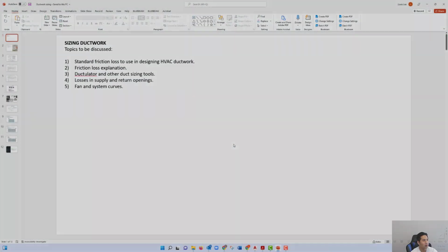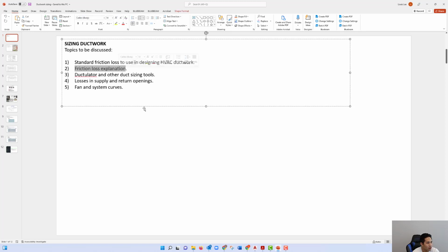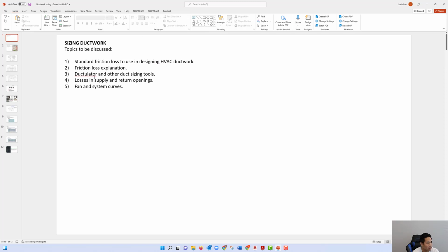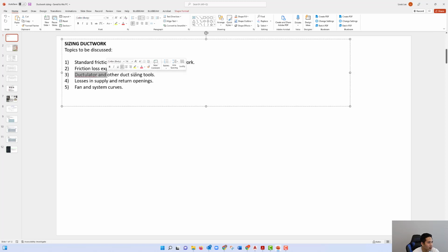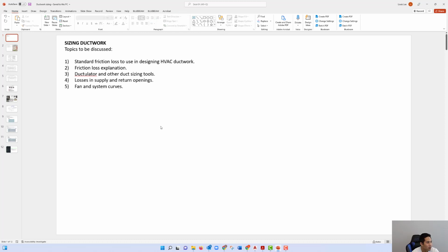In today's video, we're going to talk about sizing ductwork, and we're going to talk about these topics here. First is the standard friction loss that is used when designing HVAC ductwork. Then we'll go into explaining what the friction loss really is. Then we're going to talk about some of the tools that are used for sizing ductwork, which is the ductilator, as well as some other duct sizing tools and applications that you can download on your phone.